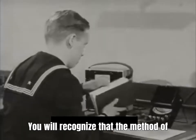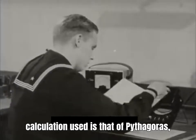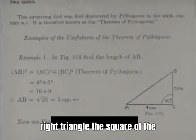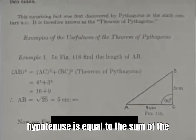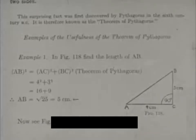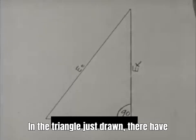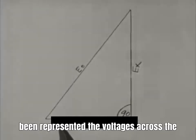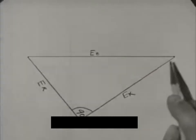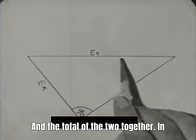You will recognize that the method of calculation used is that of Pythagoras, who many centuries ago proved that in a right triangle, the square of the hypotenuse is equal to the sum of the squares of the other two sides. In the triangle just drawn, there have been represented the voltages across the resistance, the inductance, and the total of the two together.